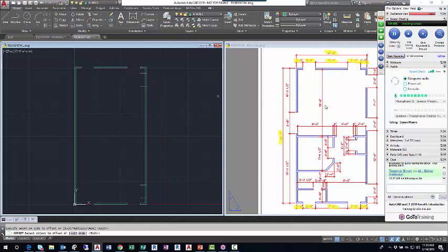And before I trim these, there's a window in between, a 3-foot window. It's not perfectly in the middle. It sits 7 feet 1 inch down the screen from the bottom edge of the top window. So I'm going to offset that bottom line down the screen 7 feet 1. So I'll go offset 7 feet 1. Enter. Left click that new line I made earlier. Move down the screen and left click. So there's the top edge of the middle window.